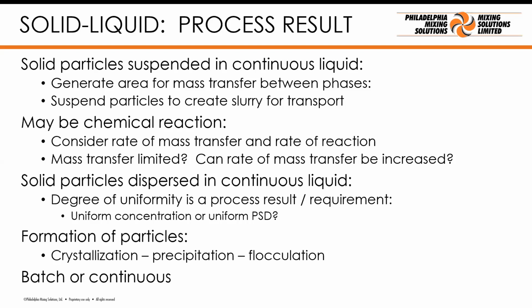In another way, yes, in our university, we don't enter in detail related with the mixing, but we always say, in order to scale up, for example, your experience in laboratory, in order to evaluate mass transfer or something like that, you can maintain the Reynolds number in order to keep the same pumping capacity.